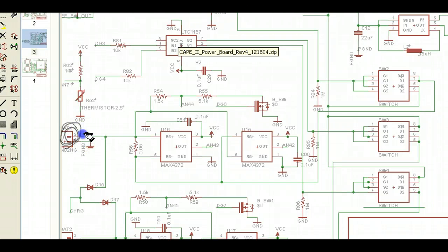The battery delivers power, and again, it goes through a resistor divider network, which reduces the voltage by about 60%. So we send the battery voltage to the PIC through a switch. This is also a little switch to ground, which turns on and off. If we want to read the battery voltage, we have to energize this thing first.